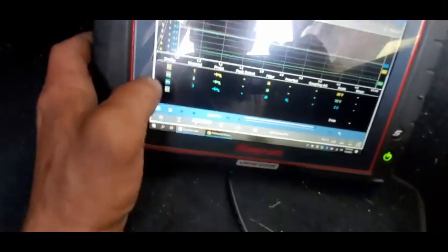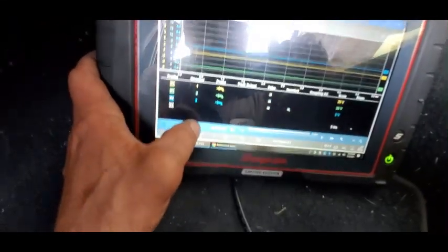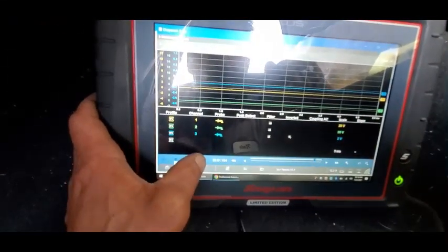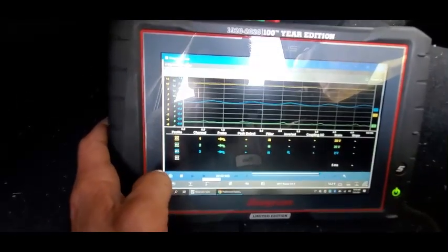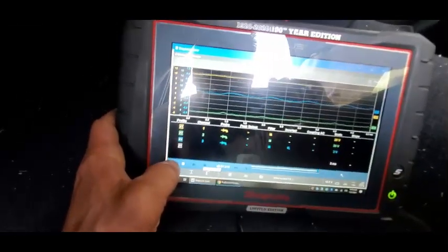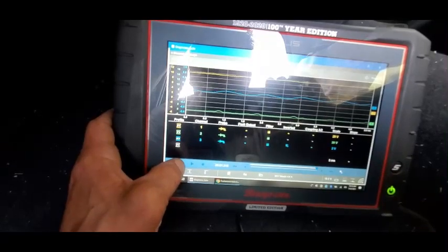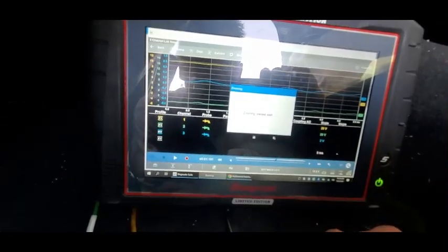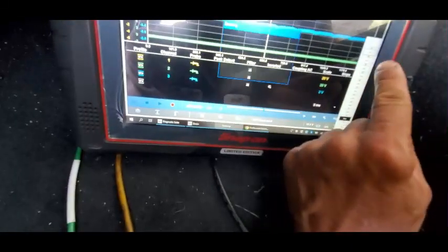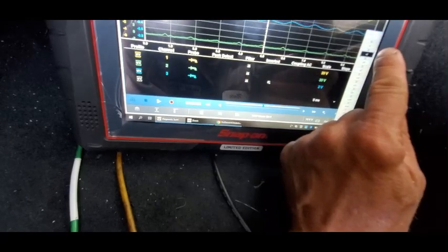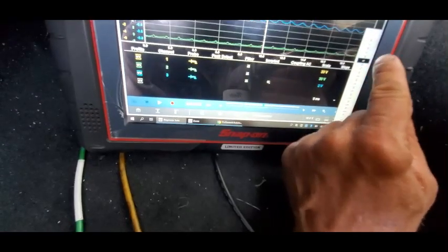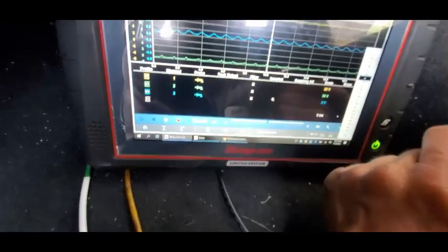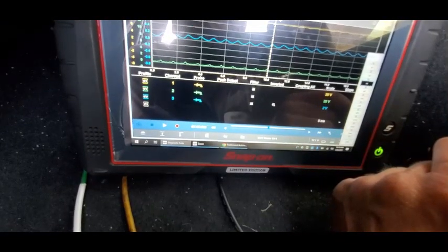We got a jump pack on her. Jumping the gun. Alright, go for it. Crank, crank, crank. There, now our battery voltage is up there. Beautiful. Okay. Settle down. Look at that. That's a nice ramp. That's a nice current capture. So what do we got there? We are pulling around 2 amps on this pump.